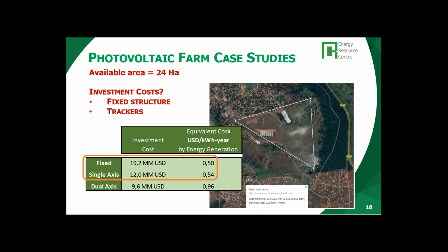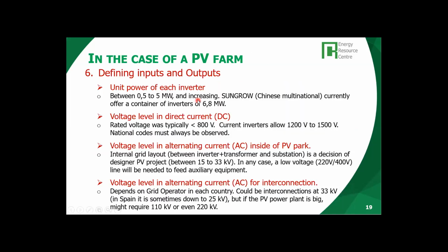Obviously, there are other aspects we need to check, many more inputs and outputs that we will now explore in a bit more detail. But we wanted to share this quick exercise so that you have a first idea of quick pre-sizing for large PV plants. All right, other things we need to consider: the power capacity of the inverters, of course.